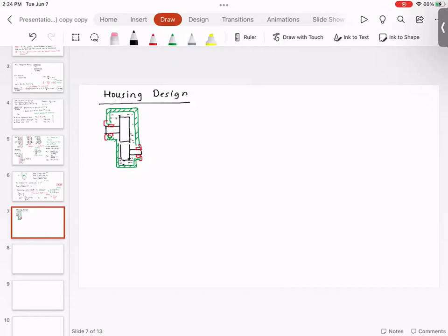The way that gear is going to work is that oil would continuously be splashed and circulated. So whatever power loss is converted into heat, that heat will be transmitted to the housing, and that heat will be dissipated from the housing.